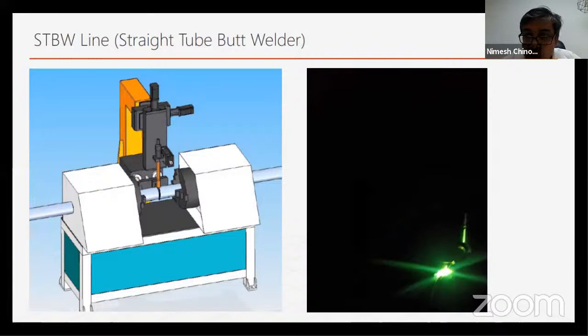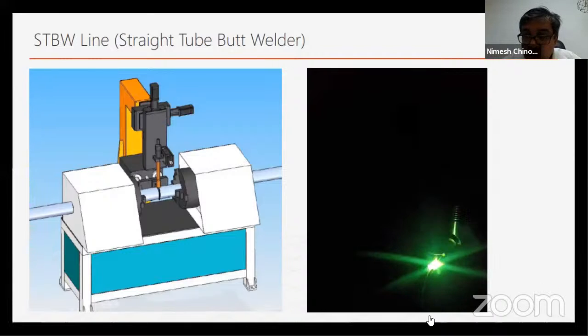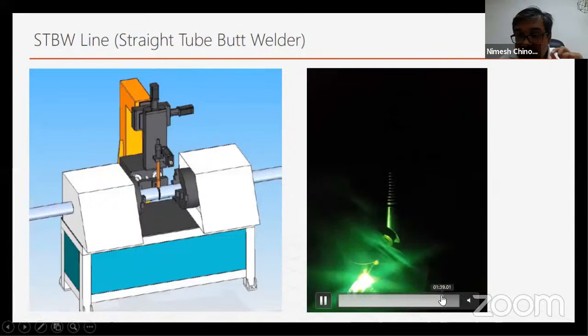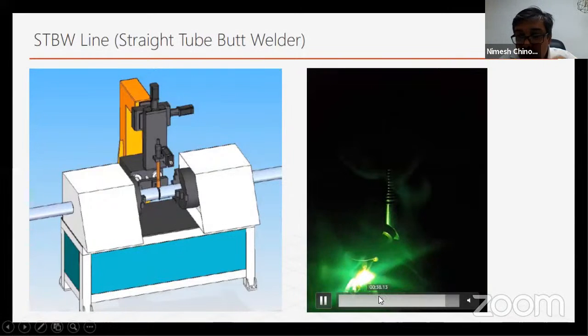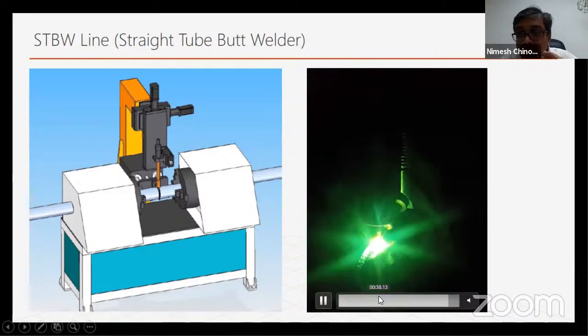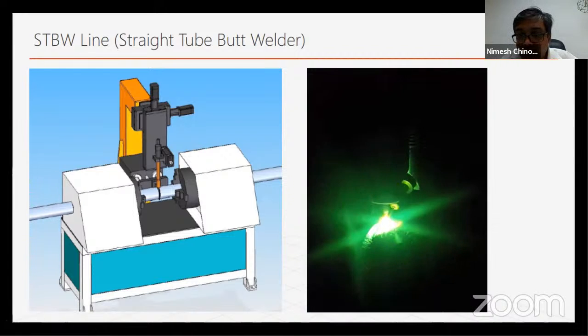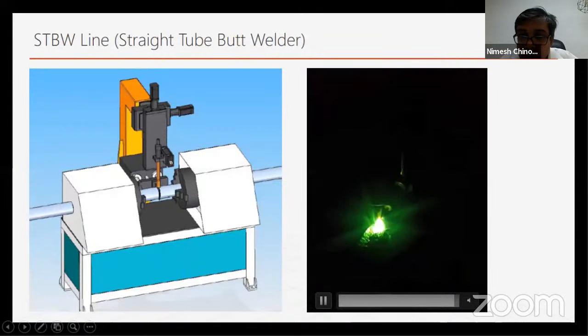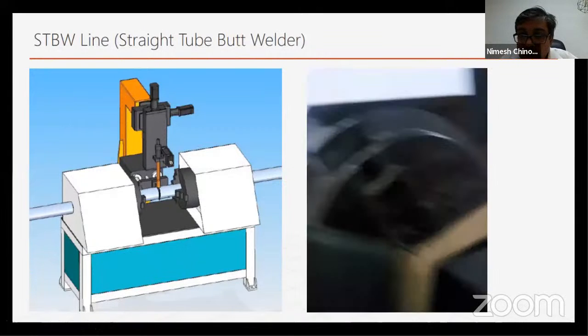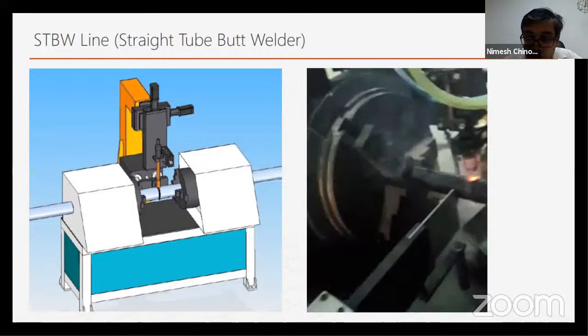Now these are for boiler tubes. They are 100% X-ray quality joints. Now your helper who understands the arc and where it should focus can do the same job of an RT welder without much difficulty now. You can see clearly the wire fed into the pool. This is the downstroke when it stops welding, so there is no crater formation, and a very easy overlap can be given.